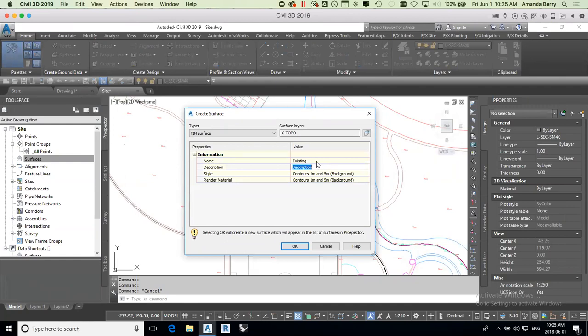And that's because they end up popping in here. And if you just name it surface 1, surface 2, feature line 1, feature line 2, you're going to lose track of things. It's like layer naming properly. So I might call this survey from GGG surveyors. And I even like to give it the date of when that survey was from, because I might eventually start getting more and more surveys that I might add in with different information.